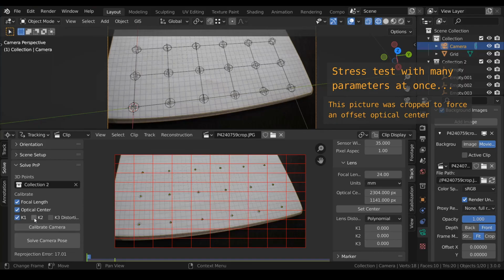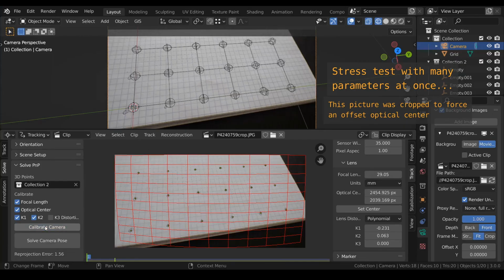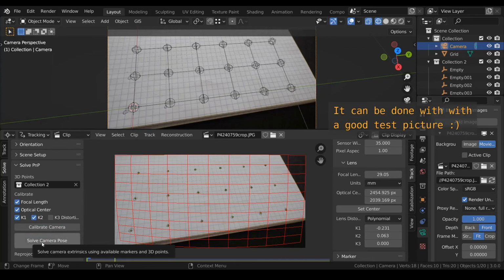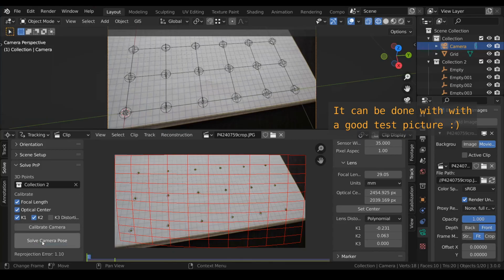Every extra free parameter is an extra unknown, which makes the system of equations more difficult to solve. The more parameters you need to calibrate, the more point pairs you will need to find a solution, and also the more sensitive the results are to small positional errors in the placement of the markers. Specifically for radial distortion coefficients, it is best to place a significant amount of points in areas that project to places away from the image center, so closer to the edges of the picture. These are the areas affected the most by the radial distortion.